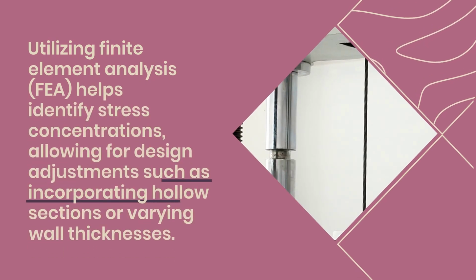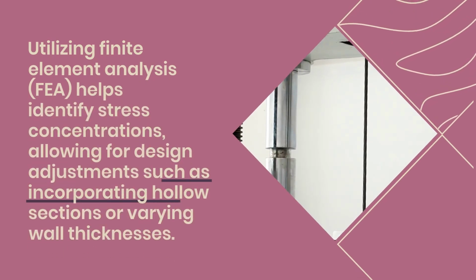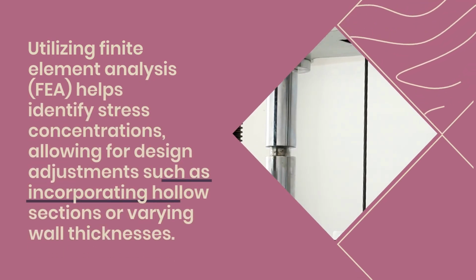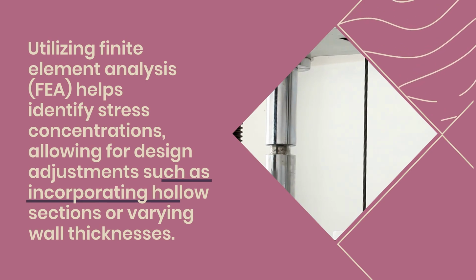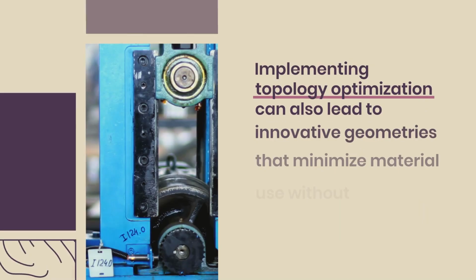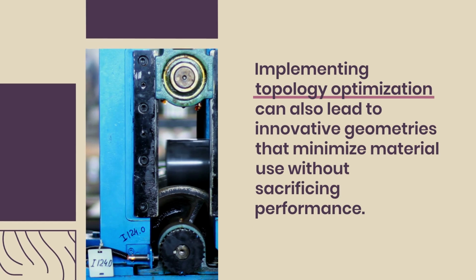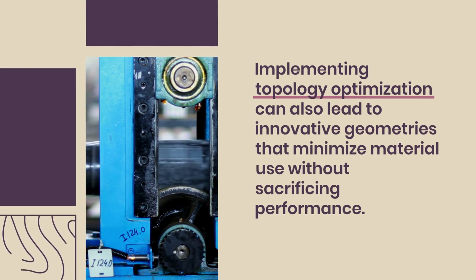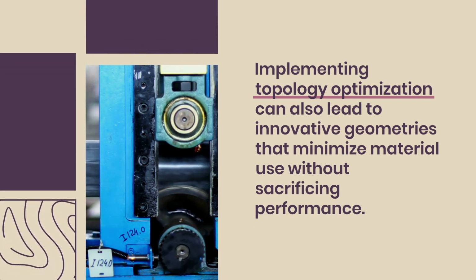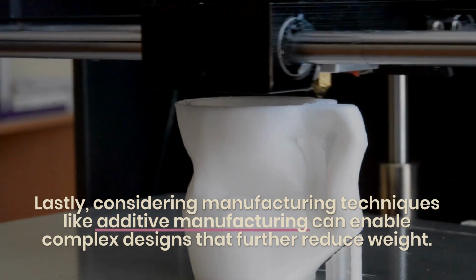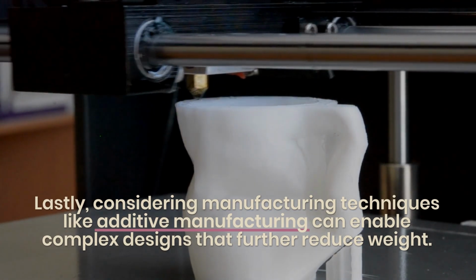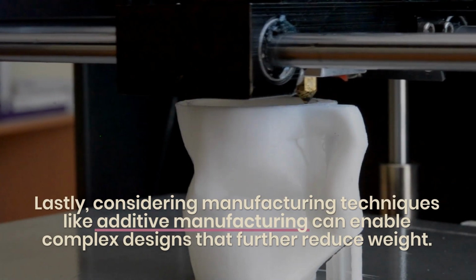Utilizing finite element analysis, FEA, helps identify stress concentrations, allowing for design adjustments such as incorporating hollow sections or varying wall thicknesses. Implementing topology optimization can also lead to innovative geometries that minimize material use without sacrificing performance. Lastly, considering manufacturing techniques like additive manufacturing can enable complex designs that further reduce weight.